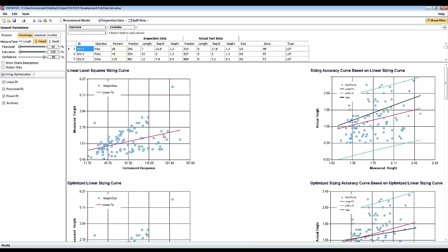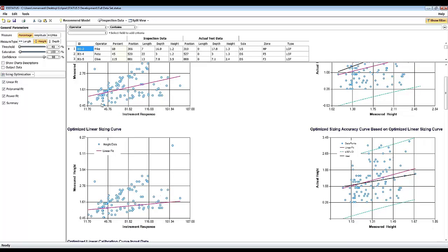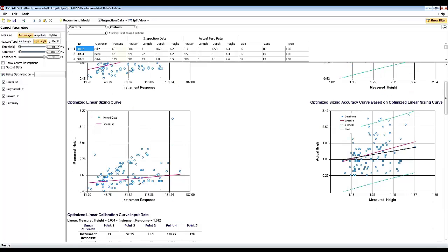And ideally, if you change your initial interpretation of the amplitude versus size by changing the equation of this line, you might be able to trick the instrument to get measurements way closer to the ideal line. And that's what we did here. Instead of using the best fit, we use another fit that we optimized, and this optimized fit would give you a measurement result which much more closely matches the ideal scenario.